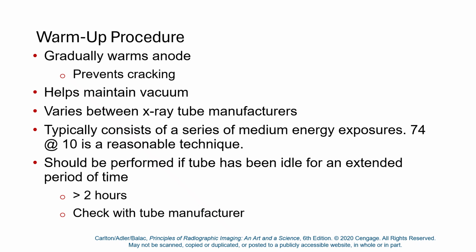If the tube has been resting or idle or not being used for an extended period of time, anything greater than 2 hours without exposures, that's an idle tube and it's assumed room temperature, so it's a cold anode. You should really warm it up before you start taking large technique exposures on that.